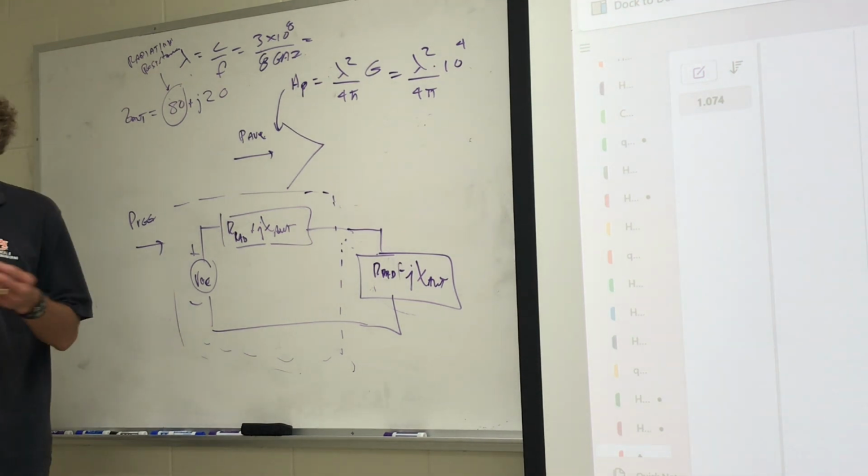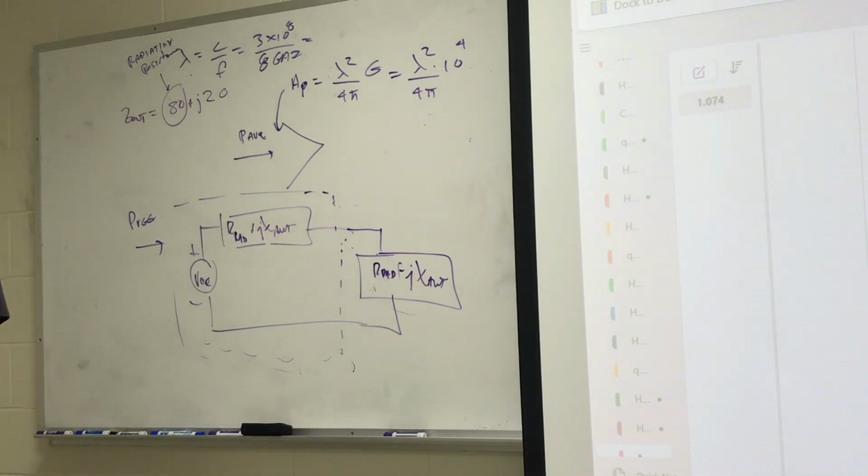This is a Thevenin equivalent. Remember, what did you have to do? You remove the load, right? You found the V open circuit across anything that you want a Thevenin equivalent. Then what do you do? You find the internal impedance. You short the source out, right, and you look at the internal impedance.